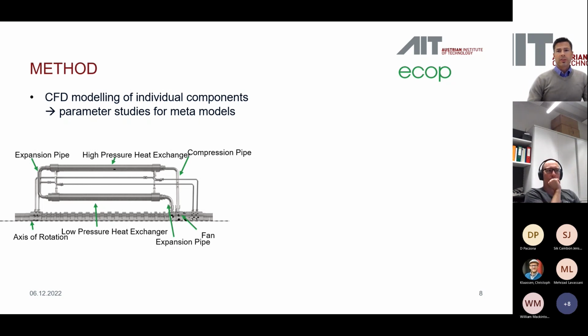The tool we used was OptiSLang. This is an add-on of ANSYS Workbench, and it delivered meta models generated directly from the CFD parameter studies. And the parameter studies had automatically chosen parameters for an adequate grid for this meta model in the end.